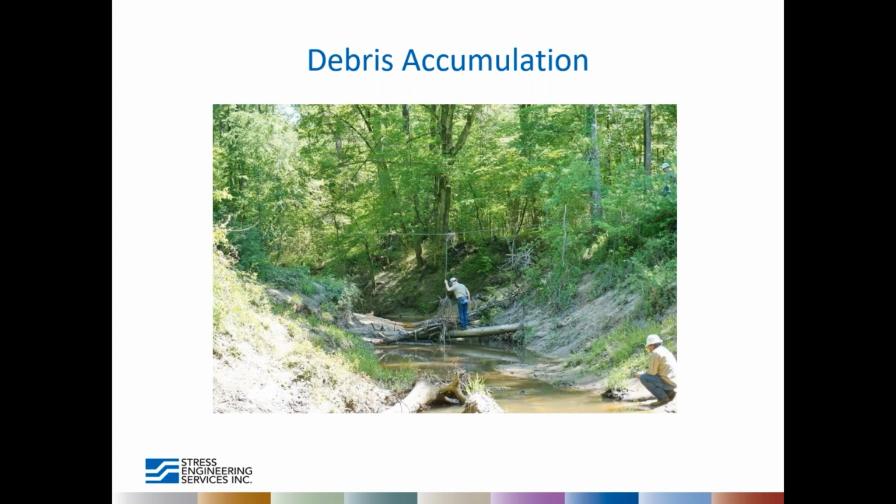I don't know whether you want to consider the person standing on the pipe to be debris accumulation, but what was interesting in this case was that they installed a cable support to try to stop the pipe from bending under steady load. But what happened instead is that the cable itself collects debris, and you can see that way up at the cross connection of the cables, there's debris there as well, indicating that even the cable was underwater at some point.